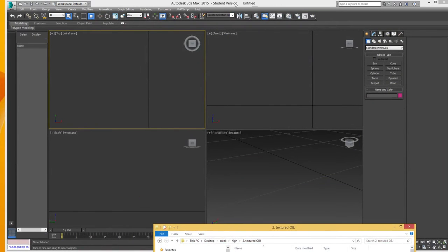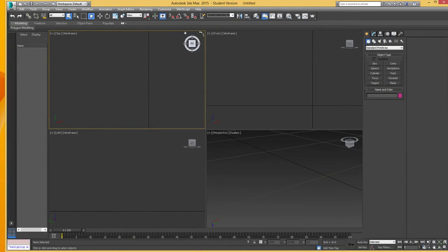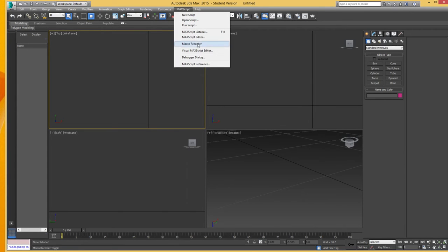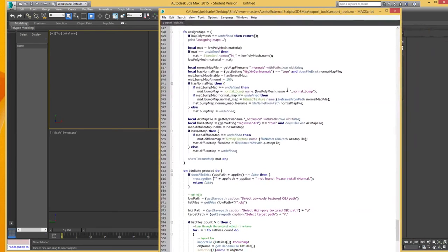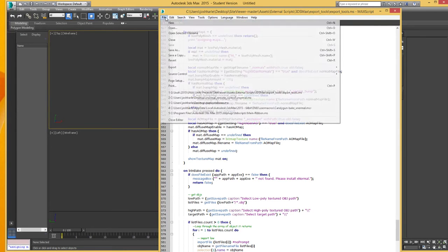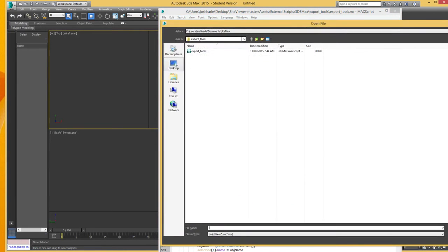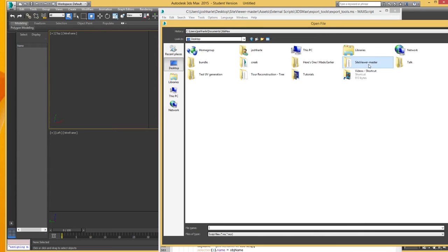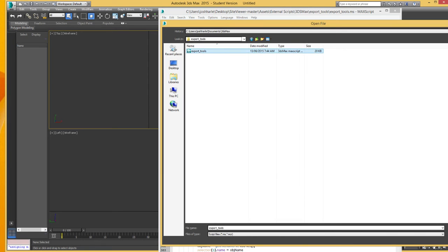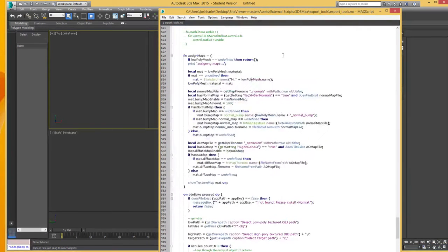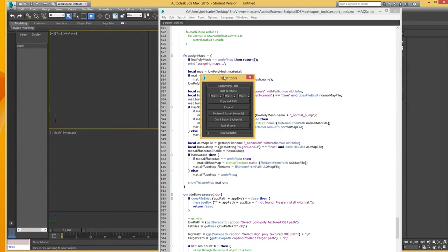So, okay, go back into our 3ds Max, go into your Maxscript editor. If that script that we were using before is still open, then you can just leave it. Otherwise, we know where to find it. It's just in your SiteViewer folder, Assets, External Scripts, 3ds Max, Export Tools, and then Export Tools. Okay, we'll hit Ctrl+E again to open up the little box.